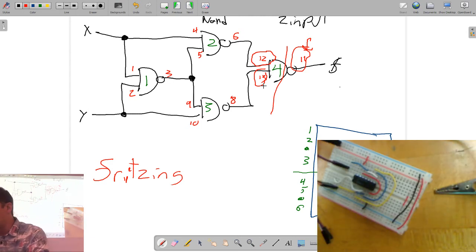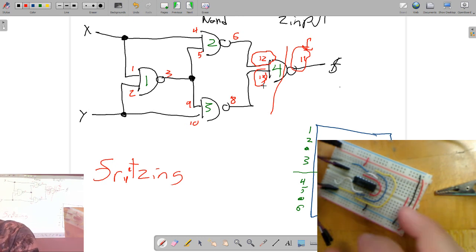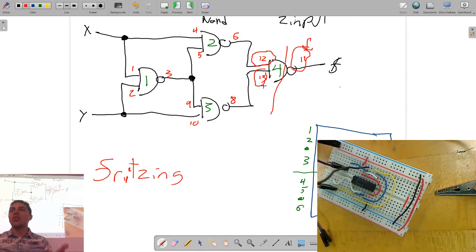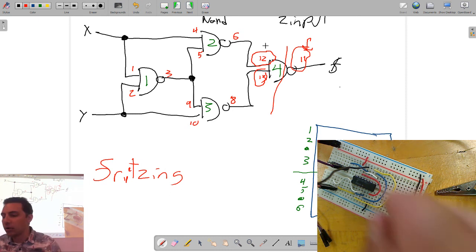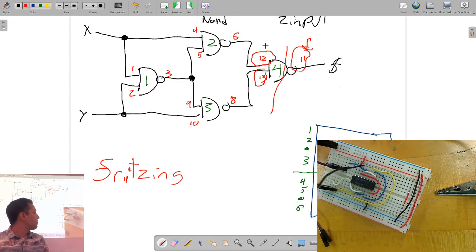And with a little testing wire, I'll come over here and I'll look at pin 12, 13, and I'll look at it on the logic analyzer. Now, either 12 will be correct, it'll have the correct waveform shown, or it'll be wrong. Now, if it's correct, then I would move on to pin 13, right? And I'd look at pin 13. And either it's correct or it's wrong.